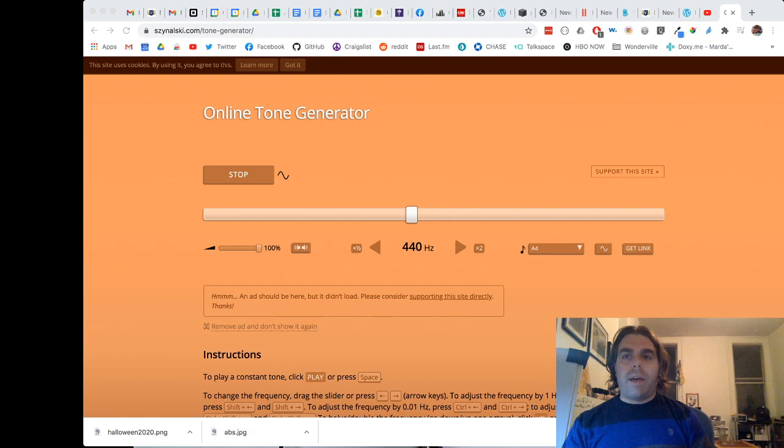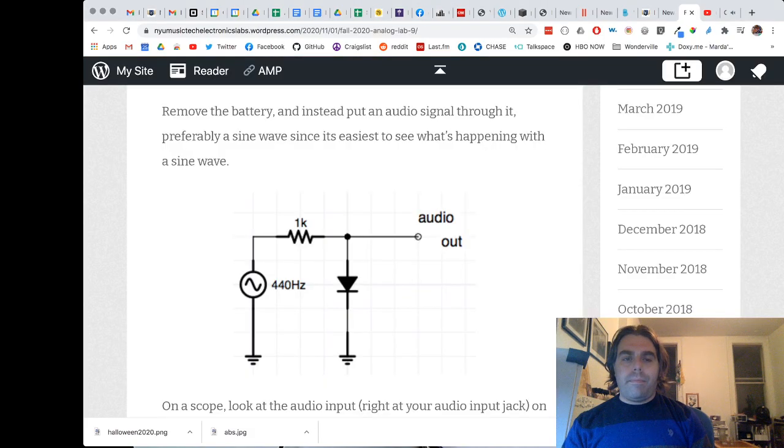So basically, let's go back to our lab. The first time we plugged in this diode with our battery, we measured the voltage, and we got something like around 0.5, excuse me, 0.6 volts. What that means is the diode has what's called an on voltage. It's the voltage that it needs to exceed in order to kind of activate.